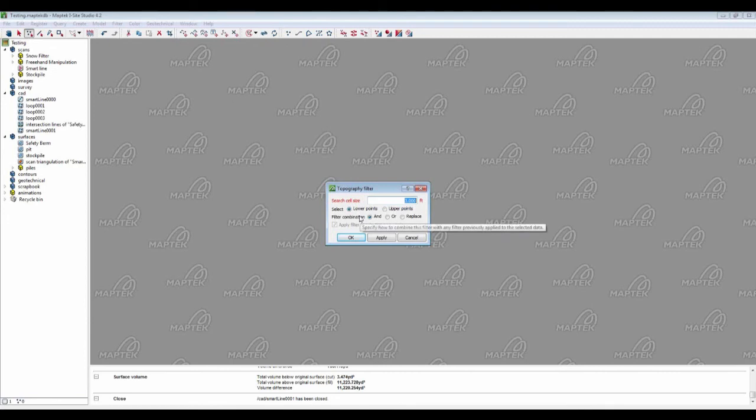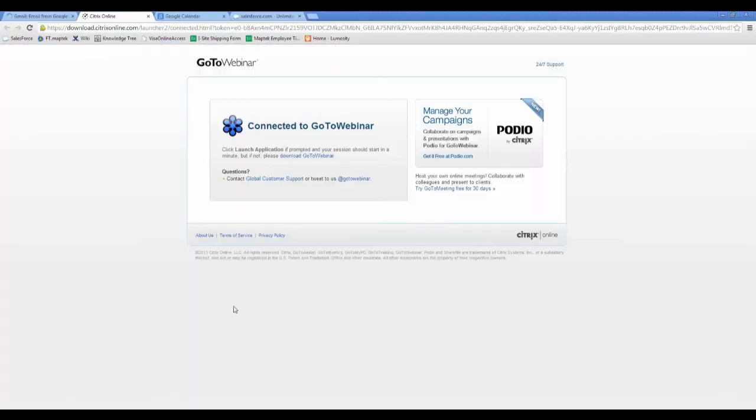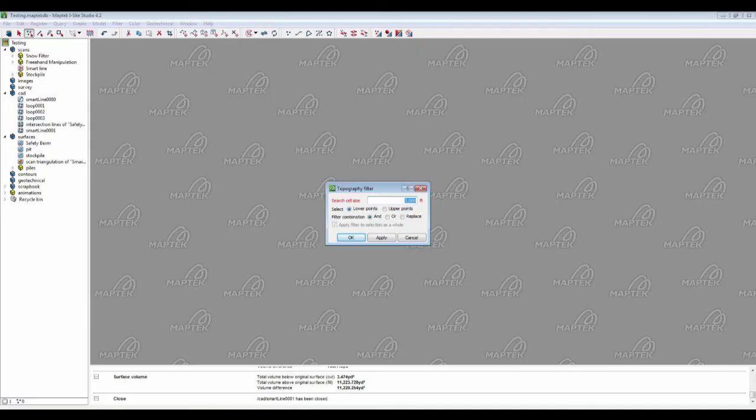Generally, you've got some points on the bare ground beneath that, and rather than going through and cropping all the way, you can just select the area with a large amount of vegetation, apply a high or a low topography filter based on what your needs are for the triangulation, and it will get rid of all the points within that cell size that are higher than the lowest. Yeah, it'll keep the absolute lowest one. So that can really help out with tree cover.